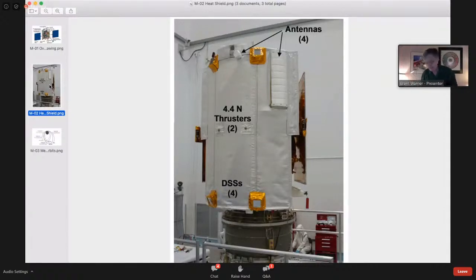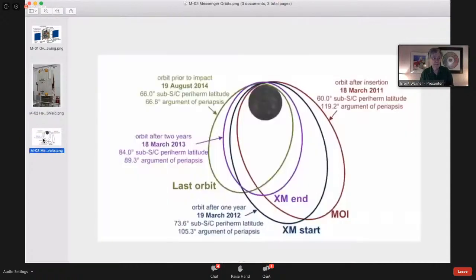Okay, now the orbit of MESSENGER is part of its thermal system. It spends about 30 minutes passing between Mercury and the sun and getting heated up. Then for the rest of the 12 hours of its orbit when it first started, or 8 hours towards the end of the mission, it gets away from Mercury so it can cool off.